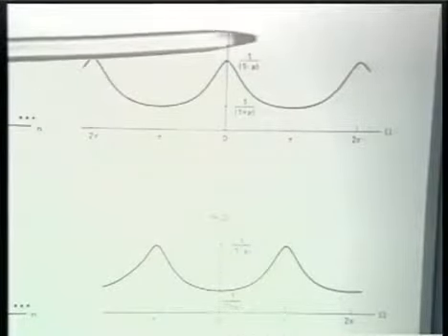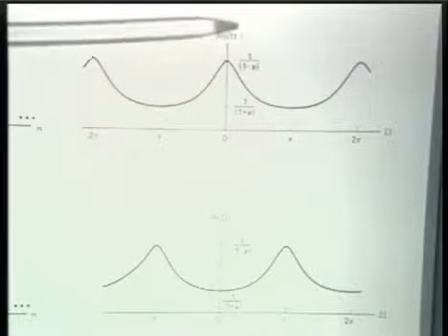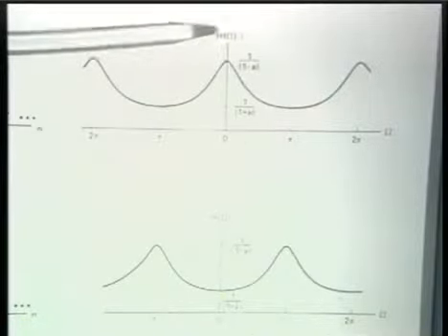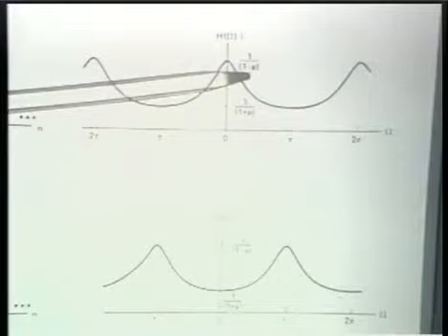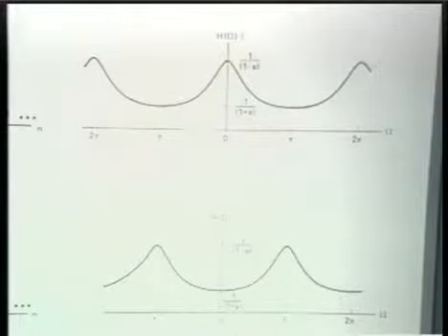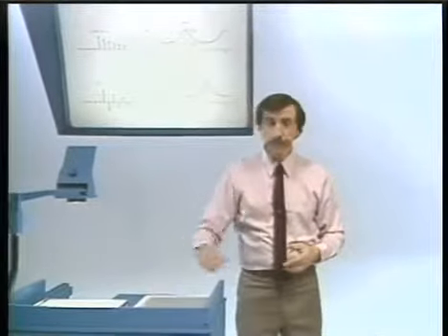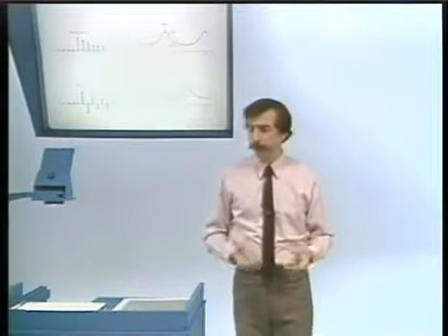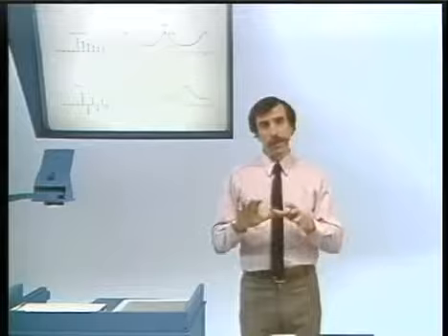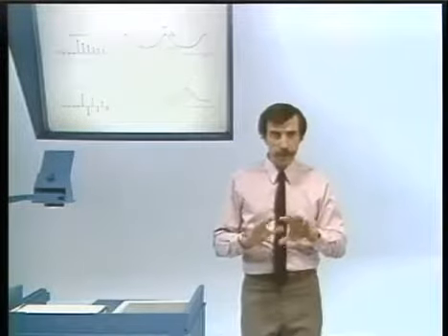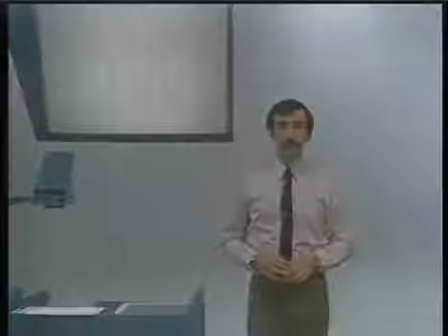As A is positive, we start to retain mostly low frequencies, and the larger A gets, but still less than 1, the more it attenuates high frequencies at the expense of low frequencies. So let's watch the filtering first with A positive, where we'll see it behave as a low-pass filter, and then with A negative, where we'll see the difference equation behaving as a high-pass filter.